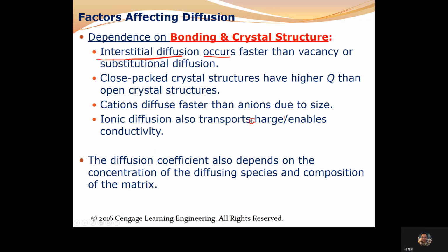During charging, when you plug in your cell phone, the lithium ions diffuse through the separator and the electrolyte to the anode, and the electrons pass through the outside circuit. When you start to use your cell phone, the lithium ions move from the anode to the cathode. The same thing happens, the electrons pass through the external circuit.